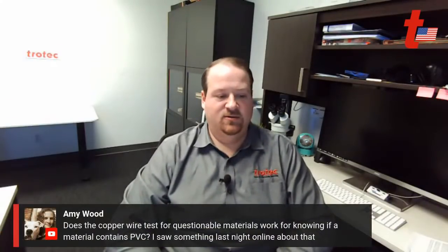Is it safe to cut fabric with fiberglass in it? I have done this, believe it or not, and it is safe. It's not going to hurt you or the laser system. The laser does like to refract off the fiberglass, and it can be troublesome and difficult to cut. The edge quality is typically not great. It's kind of a poor finish. So yes, it is safe. It's not going to hurt anything, but the quality is not the best. Mechanical shears tend to produce a better effect. So I would test it if you're not sure it's good enough for you, depending on what you need it for. Okay, next question.